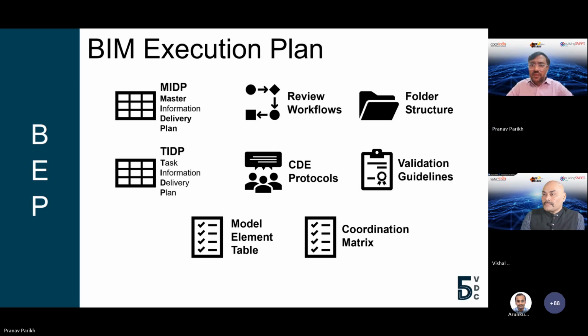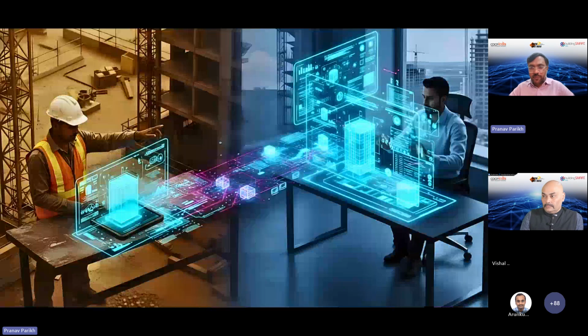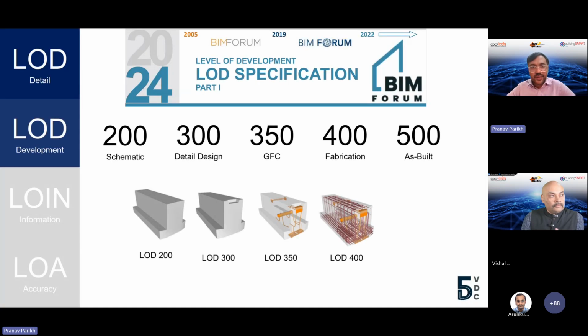Now, the most important part of the BEP that we think of is model element table, right? And that is what we want to focus on today further, because model element table is what defines how my BIM will have the information, so that we all again go back to the same logic, talk the same language, right? So let's understand model element table.